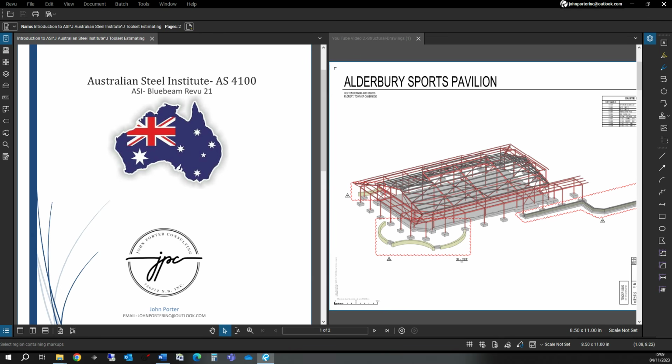Keep in mind that the standard operation is all based on AISC and CISC. The major difference only comes from the profile types or the naming that they're using out there for different assemblies. Like for columns, we're used to using W's. Out there, they'll be using UBs and UCs and WBs, WCs. So this is what I had to modify in my tool sets so that I had the same sizes and profiles as what they have out there.